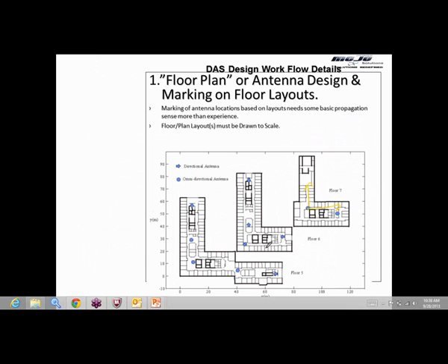Okay. So similarly, this is an important antenna position. Usually this is installed over here because over here there are elevators or lifts. So there's a thought process behind this marking of antennas. It's not done randomly. There is a stairway or walkway, and by installing an antenna over here, I can cover this hall and this hall, this area of this hall as well.